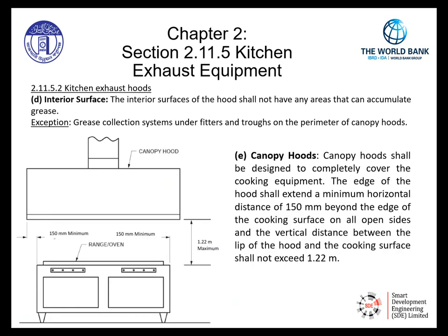Section 2.11.5.2 Item D, Interior Surface, describes the requirement for the interior surfaces of a hood in that they shall not have any areas that accumulate grease. The exception is grease collection systems under filters and troughs on the perimeter of canopy hoods.